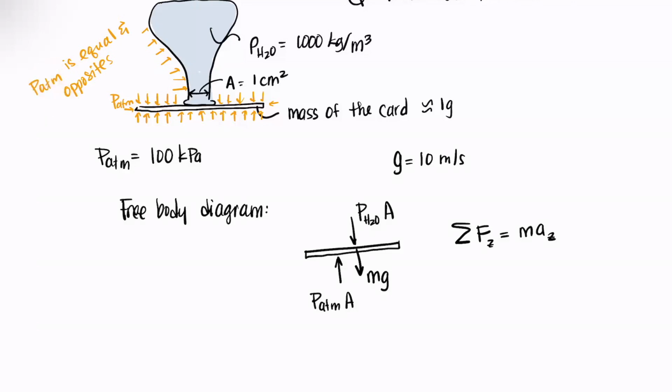Is that not legible? Hang on, I'll choose a different color. So in the highlighted regions, it's balancing itself, right? So it's balanced here and here, and it's balanced here and here, and then from side to side, right? But then we have this little segment at the bottom where it's not balanced, right? So that's the only atmospheric pressure that we actually have to concern ourselves with. You could write it down, but then you would just have P atmosphere minus P atmosphere for all the places that are not where it's in contact with the water. Excellent question. Does this make sense?